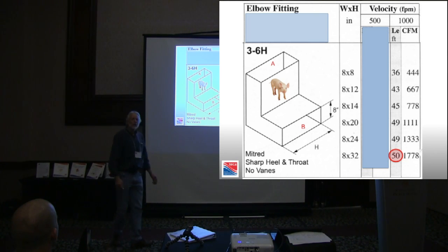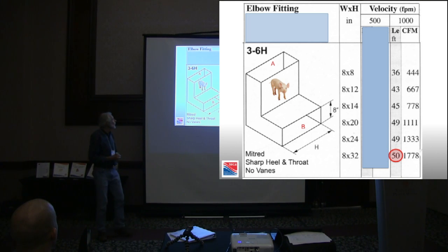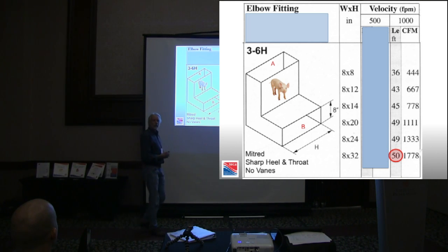Okay, well, one of the things that reduces the amount of air that you can move through a furnace is fittings. And it's not really the length of the duct that matters so much and how much air you can move through a duct system, but how many corners you're smashing that air around to do it. I'd like to take one single fitting that Gary and I have learned is the single biggest culprit for reducing the airflow through a duct system in a residence, and that's the drop elbow.